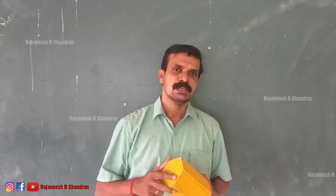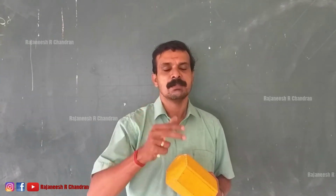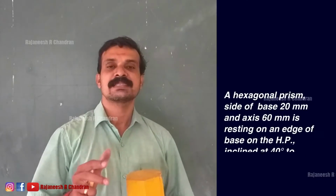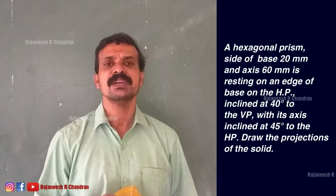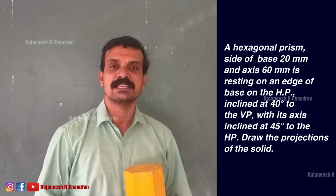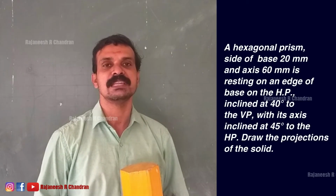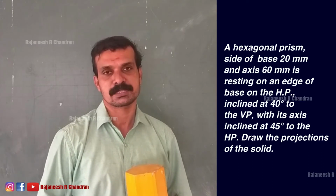In this session we are going to study the projection of a hexagonal prism. In the previous videos we have learned about a pentagonal pyramid and a triangular prism. So the question you can see on your screen right now: a hexagonal prism of base edge 20 mm and height 60 mm is placed on the ground with one of its base edges on HP, inclined 40 degrees with VP, and the axis is inclined at an angle of 45 degrees with respect to HP. So draw the projections of the hexagonal prism.